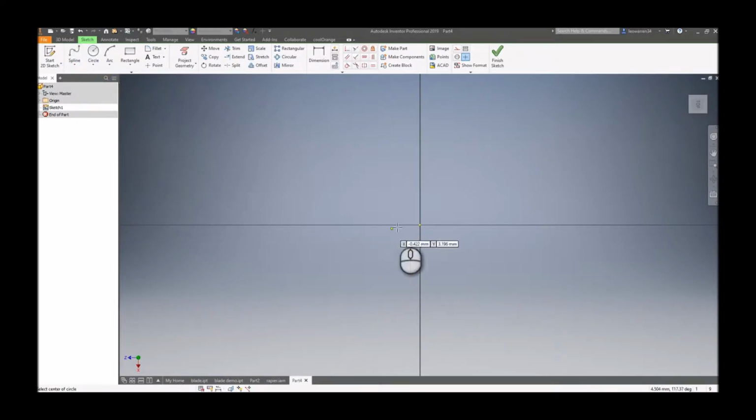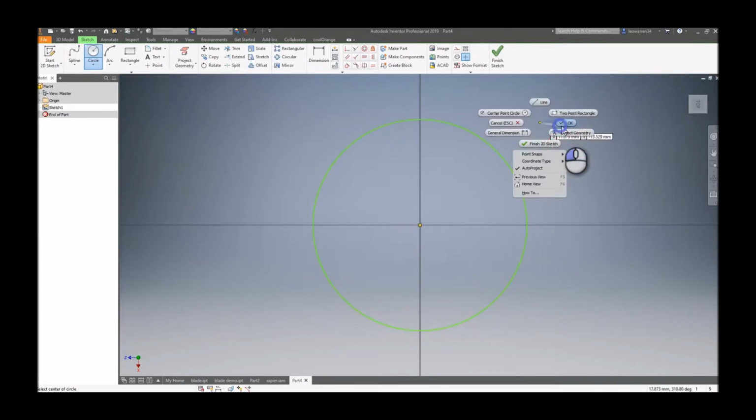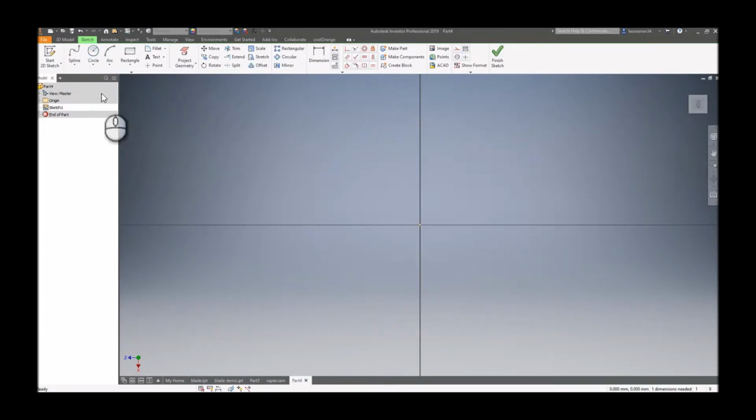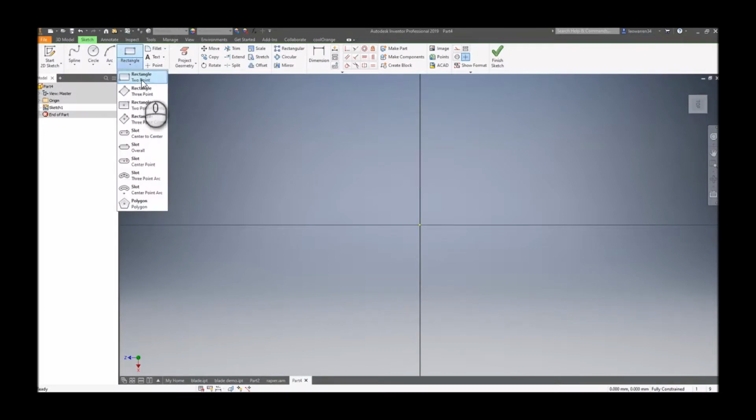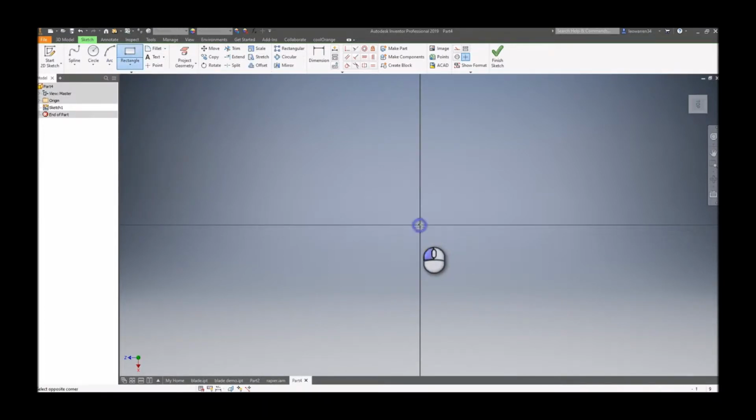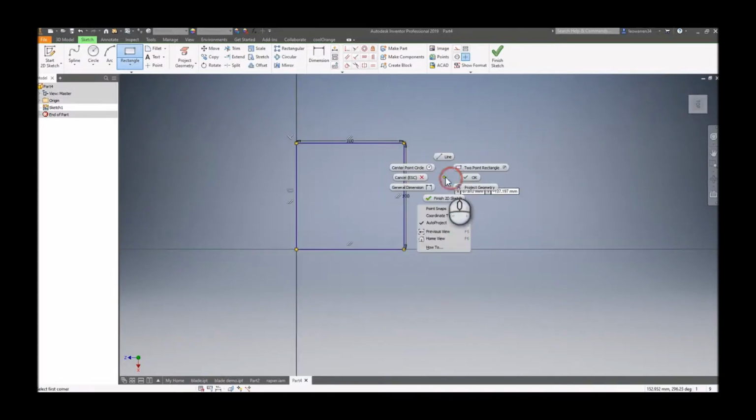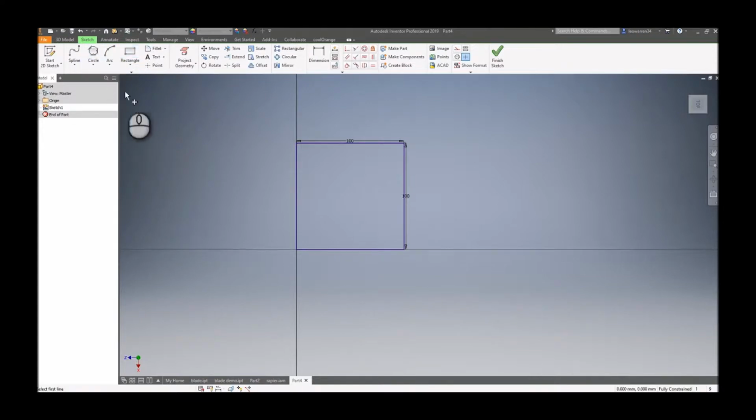And then you've got equation curves where you can define equations, and bridge curves that join curves together. You got circles where you go first way to define a center point, then circle, job done. The second one also defines a circular tangent, so let us just make a square. There we go, one square, and let's take a tangent, choose the tangent variety, and just pick 3 sides, and there you go, circle in your square. Not quite square in the circle, but near enough.